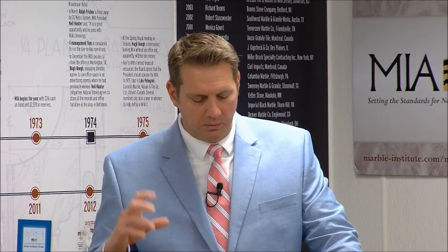So if it's cladding, it's really more relevant to what we're actually trying to do. Plus, it's not point loaded as the modulus of rupture is. We're actually using 2 points, so it more closely simulates the condition of a piece of stone being clipped top and bottom, and the wind resistance that it needs to withstand.